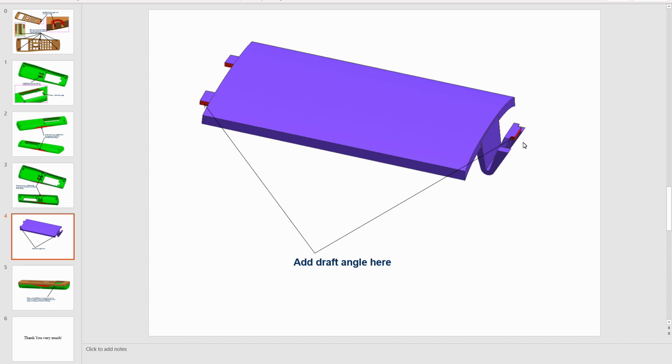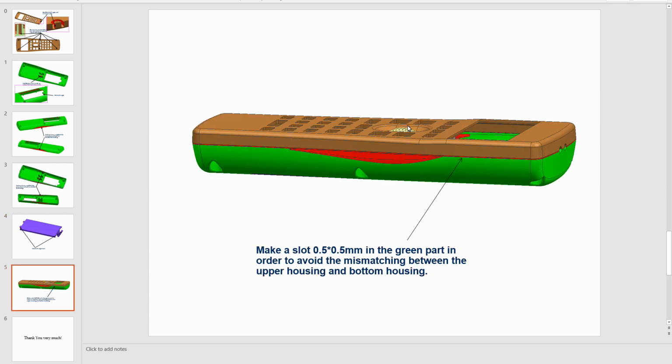One of the things about designing something like this up front is it's really hard to know until you make the mold exactly where the parting line should be, and therefore which way the draft angle should be. The final change they made is to make the alignment of the mold halves less critical, so that it looks like they fit together better even if there are slight variations along the way.